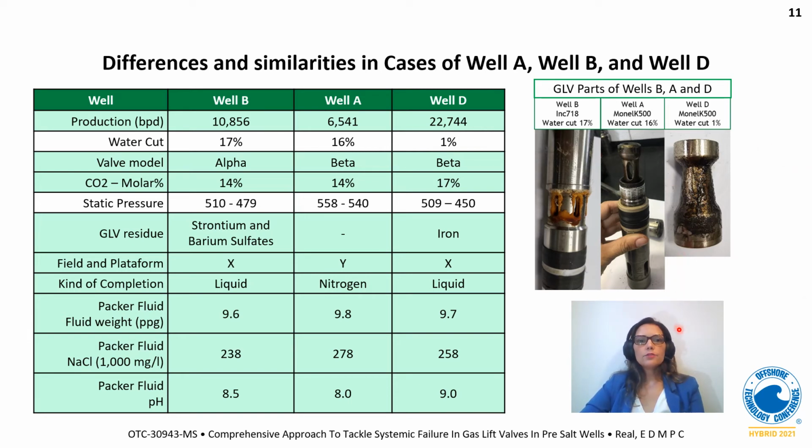The well A gas lift valve did not present residue on the outside of the valve frame. However, it was not possible to dismantle it. There was no tool for it at that time. Thus, it is very unlikely that no residue deposited in the internals of this valve, since it presented a check valve stuck in an open position, like in this picture. This indicates the valve failure, and one possible cause of this type of failure is residue deposited in the check